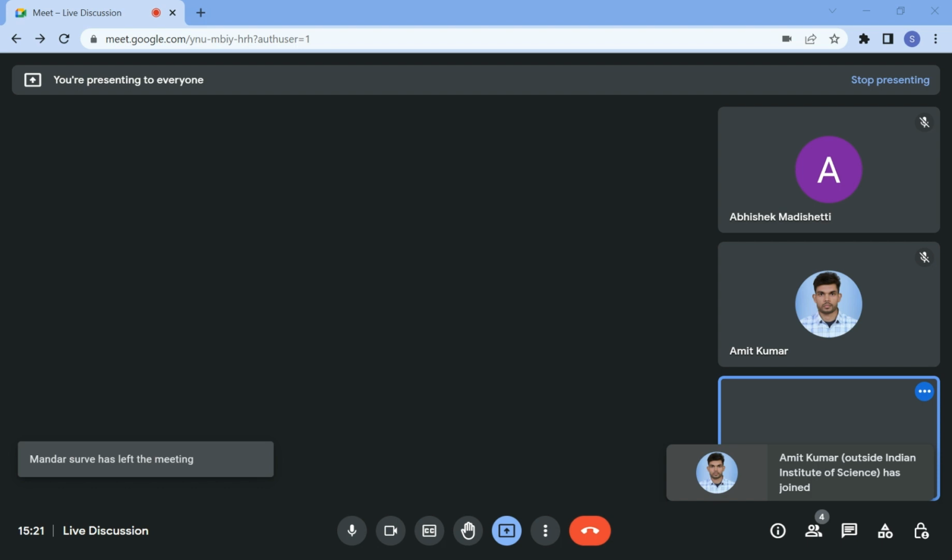So the locus of all points B which are at 45 degrees will be a circle with a radius of true length cos 45. So when you are given such a problem, I will just rub this off and now explain the procedure that is followed.